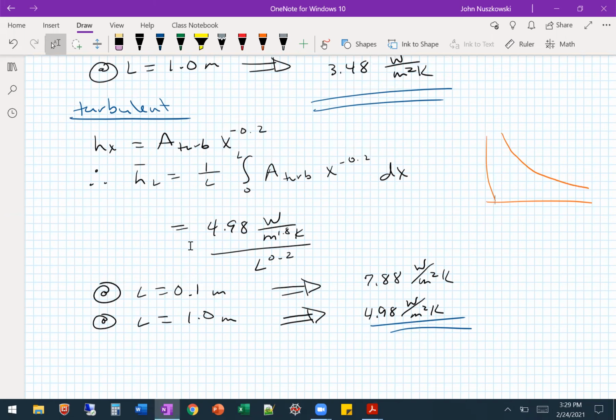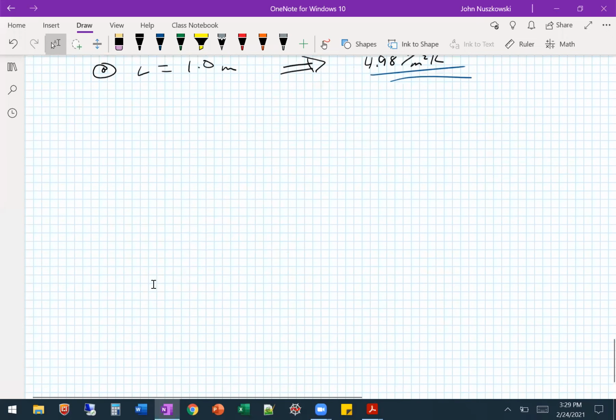Okay, I've got one last one I want to do from chapter 6. We've got 6.21. Consider laminar boundary layer flow over a flat plate. For identical flow conditions, determine the entries not shown in the table below using the fact that the velocity boundary layer thickness over the thermal boundary layer thickness is equal to the Prandtl number raised to the power n. The pressure is 1 atmosphere for each case. Hint, see appendices A4 through A6. And then they give us a table with missing information, some information there, some missing.